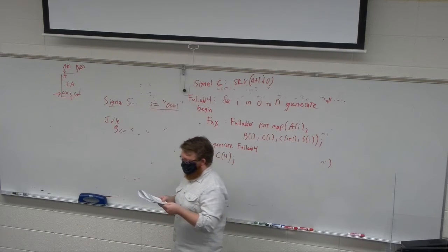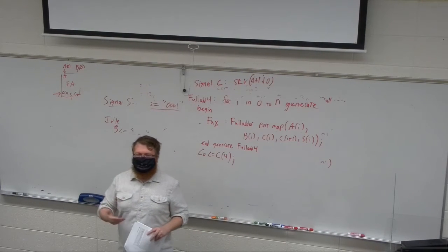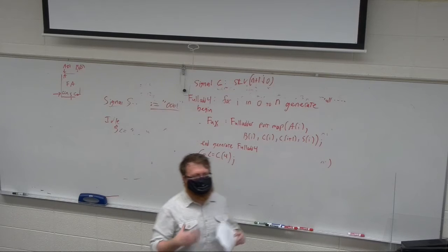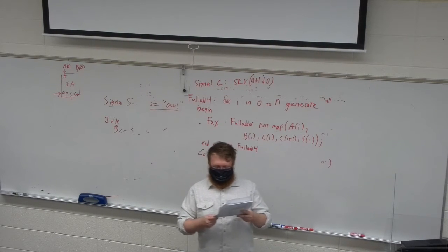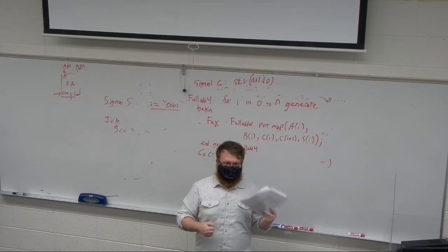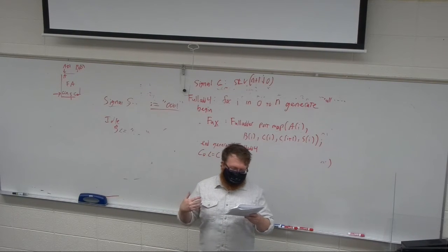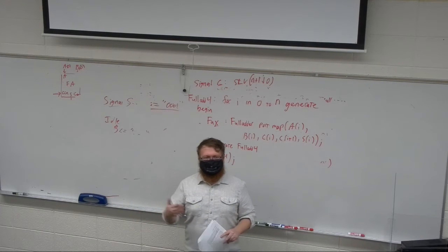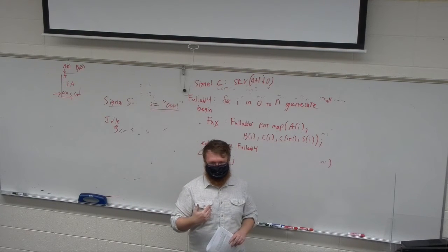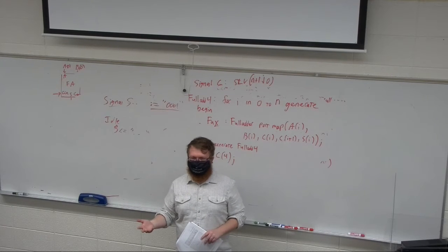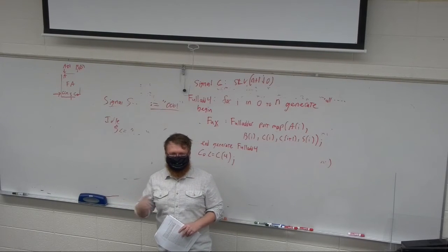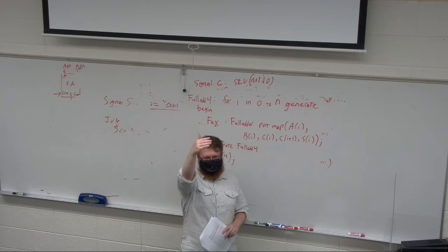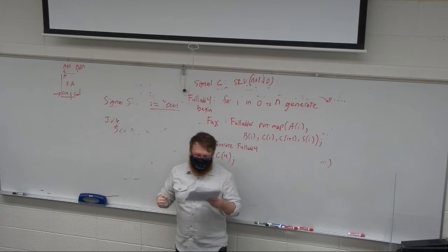The other big one is they keep the addressing modes simple. They usually pick one type of addressing mode and stick to it. The easiest one to use is direct addressing. I give an address, I get an address, right? The other one is immediate addressing. Immediate addressing just says whatever is next. So those two in combination is really common. You can say either give me this specific address or give me the immediate value. And that's what your 2700 project would have been. Those are the two types it used: load from somewhere or give me the next one, right? But you can go into other ones.